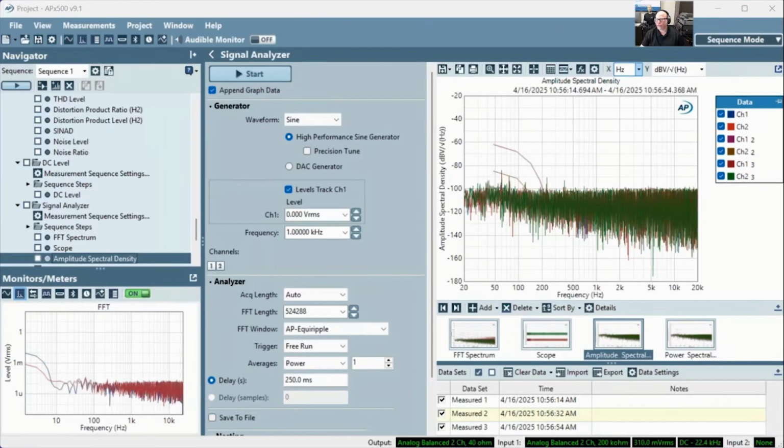The difference between the input and output load on the references tab, frankly, in all normal situations, I would only recommend using the input load reference. The output load reference refers to the dBu generator unit. dBu is a little bit archaic because it implies that you're testing a 600 ohm terminated circuit, and the generator reference refers to that.